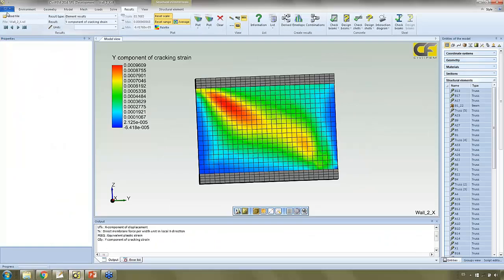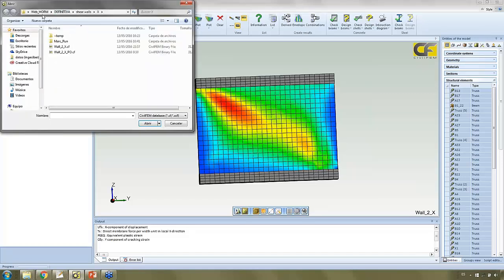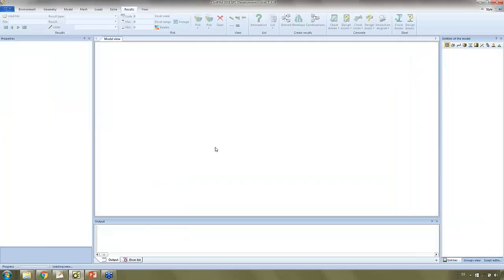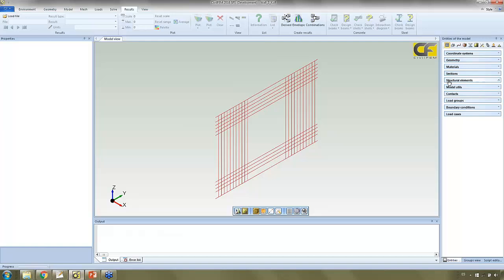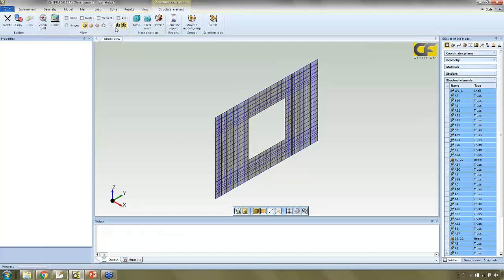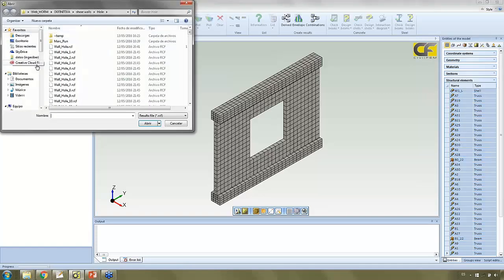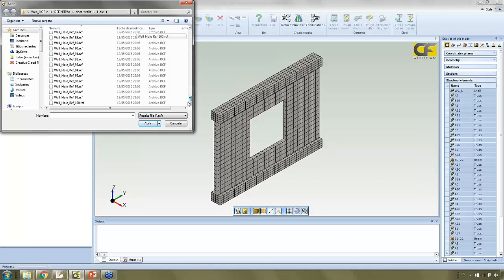Here we are going to plot the last one. The thing is, it's always easier to model the smaller structures, as we already know the forces, moments and boundary conditions coming from the big multi-story building. The resources taken into account now are always less, as you know, because we have fewer elements. And as we are adding non-linearities as well, it's better to always work with small models.